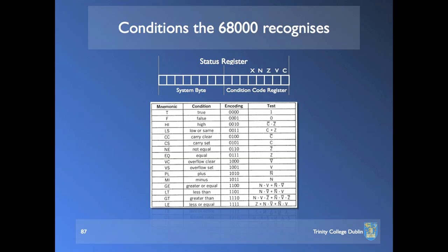Now, what I was saying was, by analogy, we want to multiply a long word by a long word to produce, let's call it, a quad word. By analogy with single-digit multiplication, which you guys have in your head, and me too, I was saying that there is word multiplication built into the silicon of the 68,000. So word multiplication on the 68,000 is the equivalent of your times tables. You have to combine it in an algorithm, long multiplication, in order to do long word multiplication to produce a quad word result. So that was the analogy that I was using.